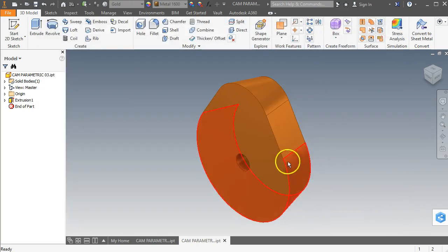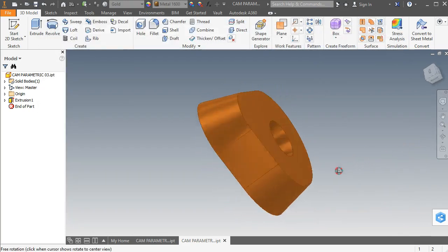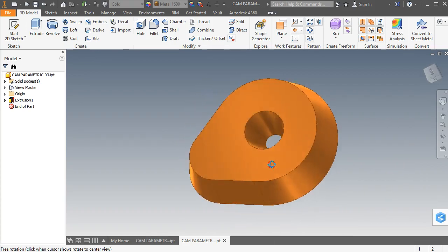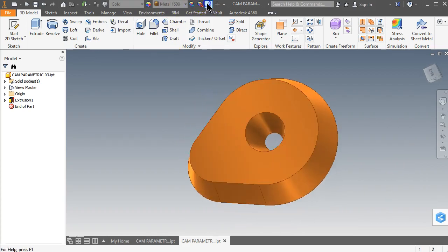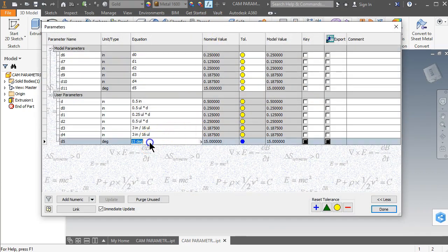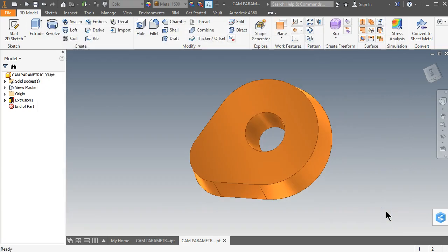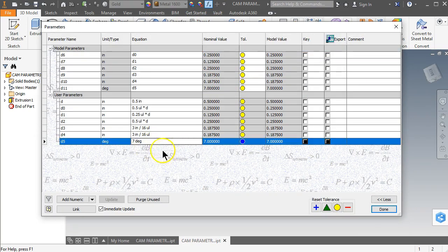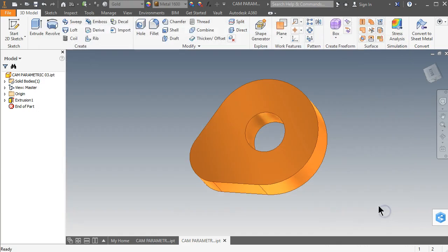And click on Done, and you can see that now instead of being straight on the sides, it's tapered out. So we have an angle as it extrudes. It either slopes in from the edges or out from the hole in the middle. And then we can change that to different values, and you can see that now it's sloped but not as much. Most of the time though, for a cam, you're going to leave that at 0 degrees. So I don't even know if that's useful to put in there, but 0 is what we want here. And we are done with that.